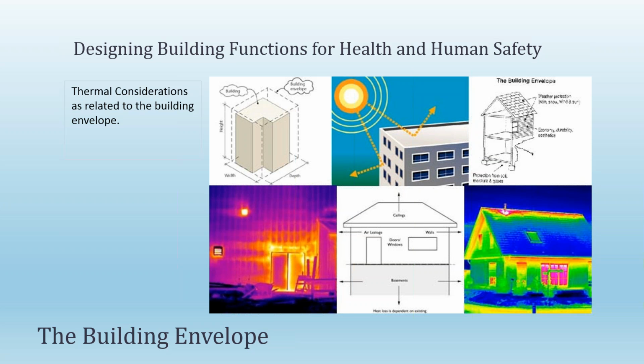So that could be window treatments, or as I said, it could be tinting to prevent the issues of hot spots that are caused by direct sunlight. Consider providing a temperature and humidity monitoring system to ensure optimal thermal comfort performance. Evaluate the use of access floors with displacement ventilation for flexibility, personal comfort control, and energy savings. Provide individual air and temperature controls at each workstation. So that's getting fairly specific.